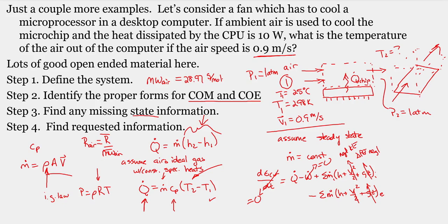Okay, so your project, before you look at the next segment, is for you to determine the density of air at the entrance conditions to our question here. And I want you to be very careful about your units. I've given you the molecular weight of air. You need to go find an appropriate form of the units for the universal gas constant and chug through that units conversion, plug in the appropriate pressure and temperature at the entrance state to get the density.